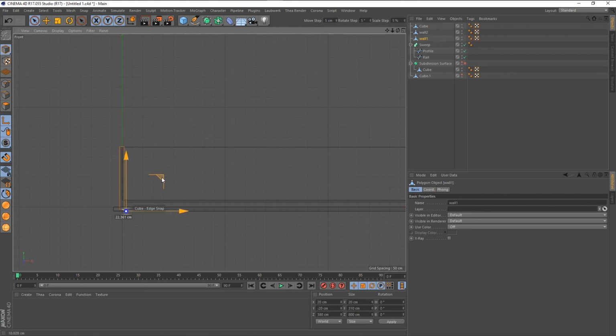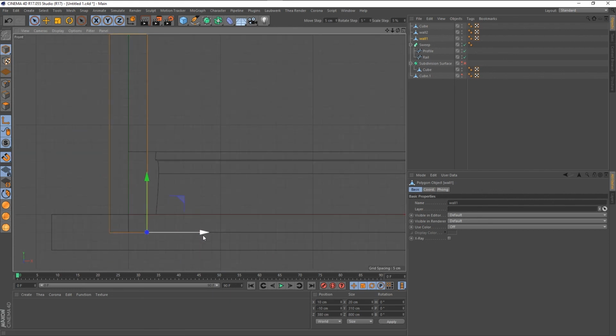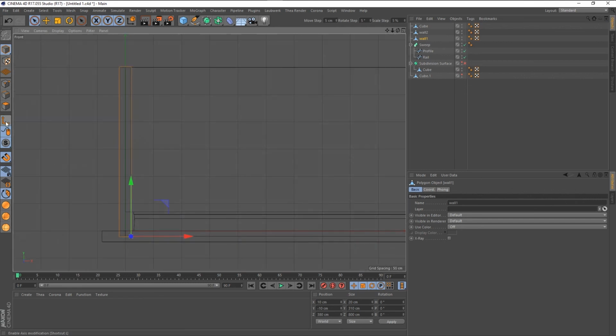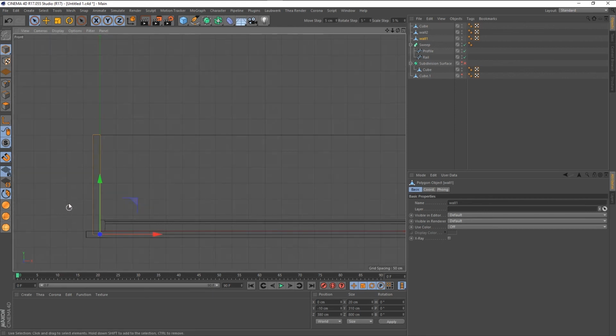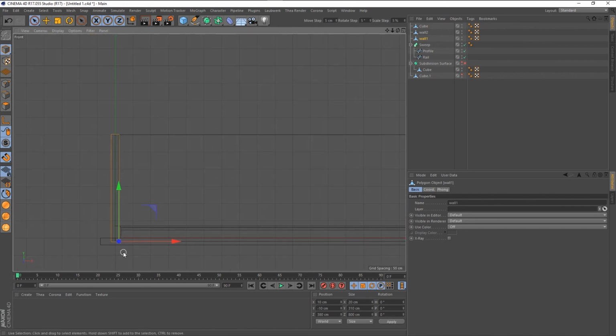So we could do that. And maybe for walls, I usually leave it at the center point of the wall, but you could move it to the inside surface of the wall. And now disable that, and we can move that 10 centimeters. And now you see why the quantizing is very handy. Okay.